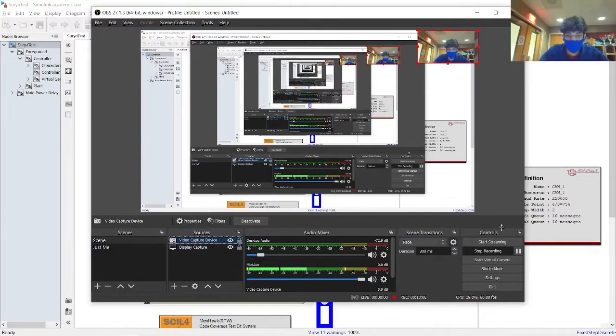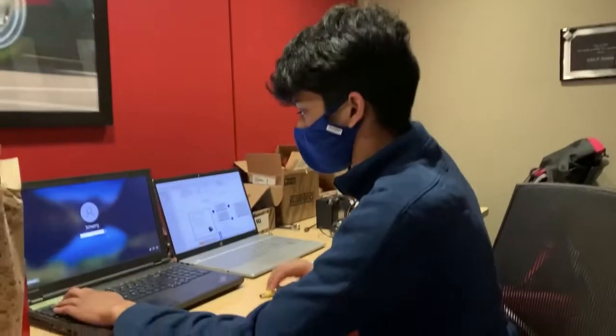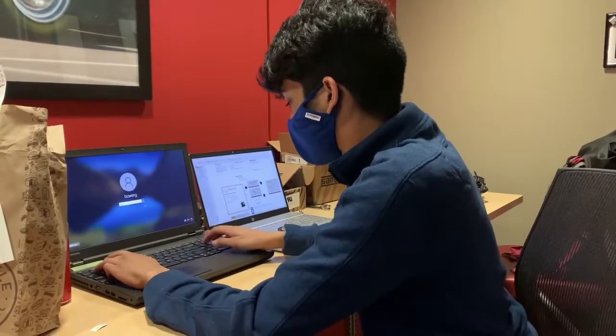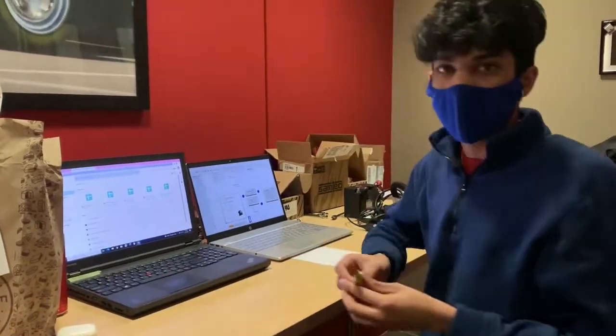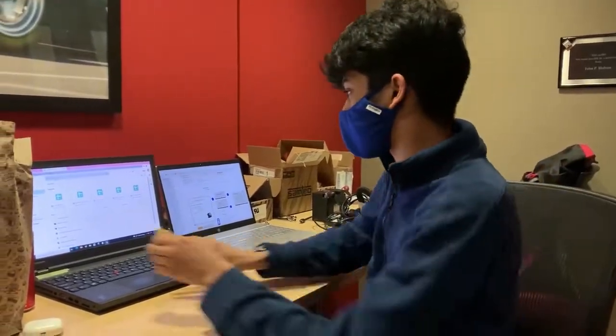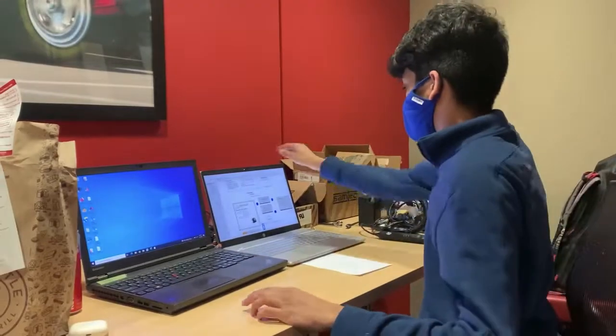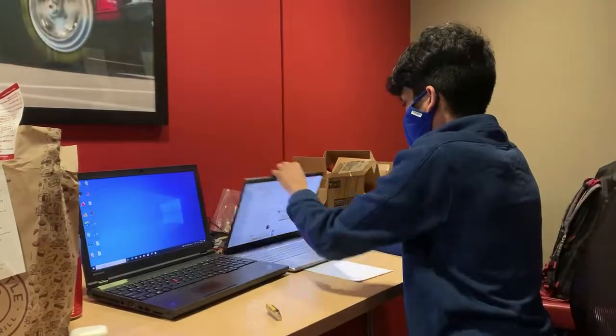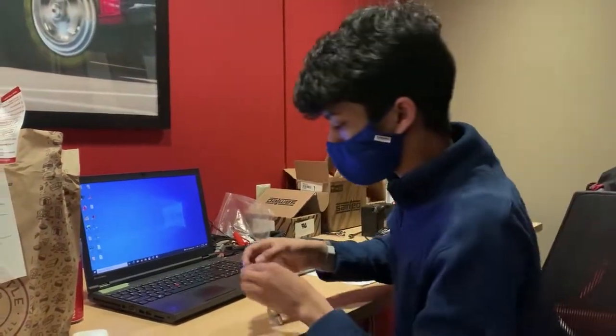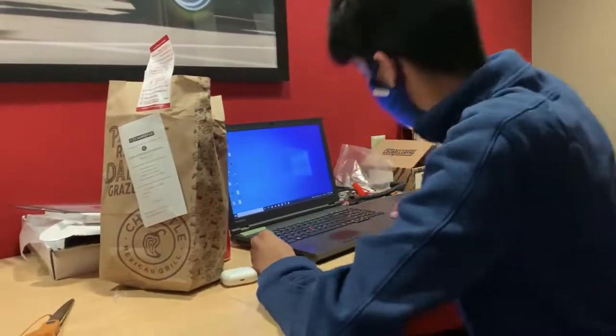So now we're going to go over to the other computer. Alright, so now we have our SRC and DLL on this flash drive. We're going to get it onto the computer that actually does the flashing. So first thing to make sure is you have the MotoTune key plugged in. So we'll plug it in here.